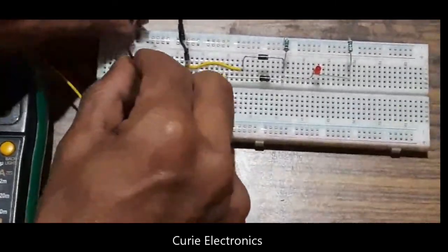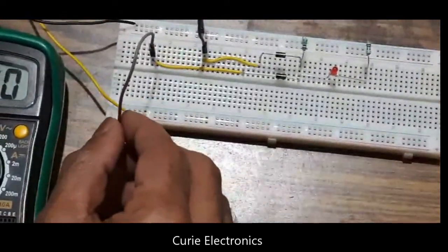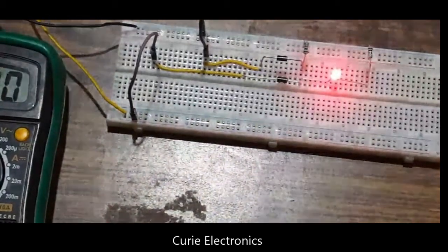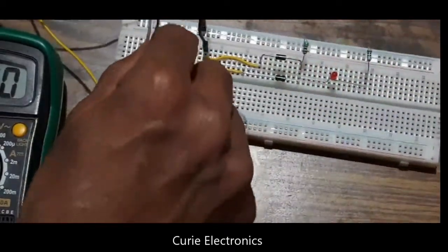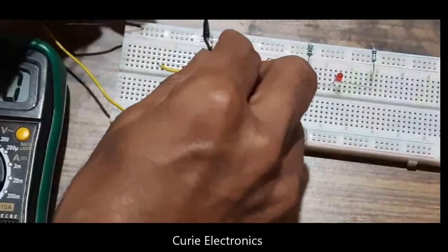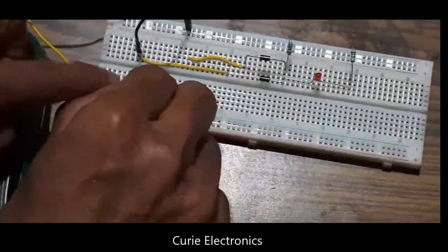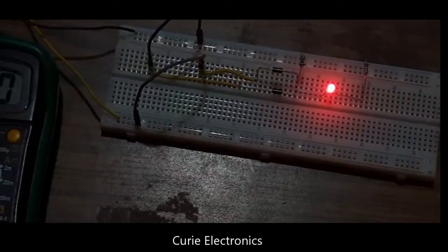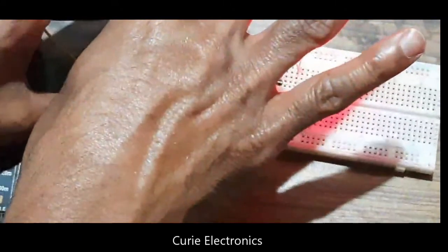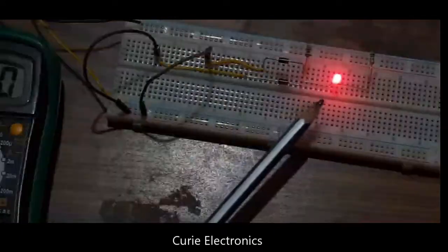Now we will give one input low and another input high. One input is connected to low, the other input I am making high. Now the LED is on. This is what we expected from an OR gate. Now we will interchange the combination, so we get the 1-0 and 0-1 combinations. Our high should go to the other input. Now this is also on. The only combination left is 1-1. So we make the 1-1 connection now. Both inputs are connected to high and our LED is on.